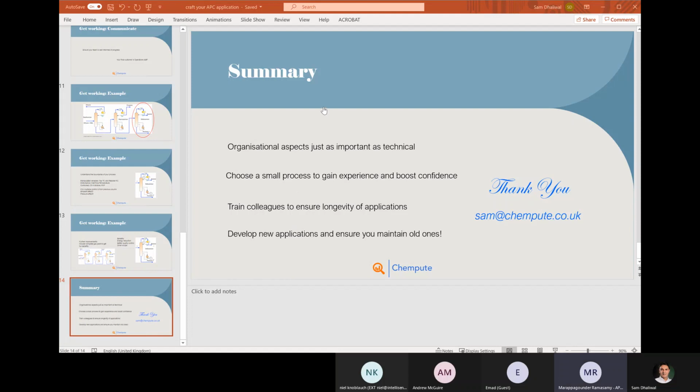In this debutanizer column, you mentioned that you will be using the top temperature TC as one of the manipulated variables. Is it common in APC applications to call temperature a manipulated variable? Otherwise, base layer controllers, we never call. It's seldom temperature is chosen as a manipulated variable. It could be either a control variable or a disturbance variable. Can you elaborate on that, please?